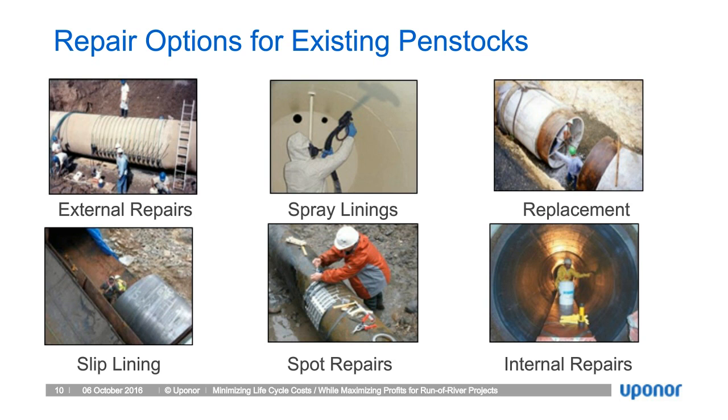repairs quickly. Below that is slip lining, which is simply taking an existing penstock and slipping a new line inside of that pipe. The advantage: you can use new materials. The disadvantage to something like this is that because you're putting an additional wall thickness into the pipe, you're going to be losing some of the diameter and possibly reducing the volume which you can push through, which would then translate to loss of power.